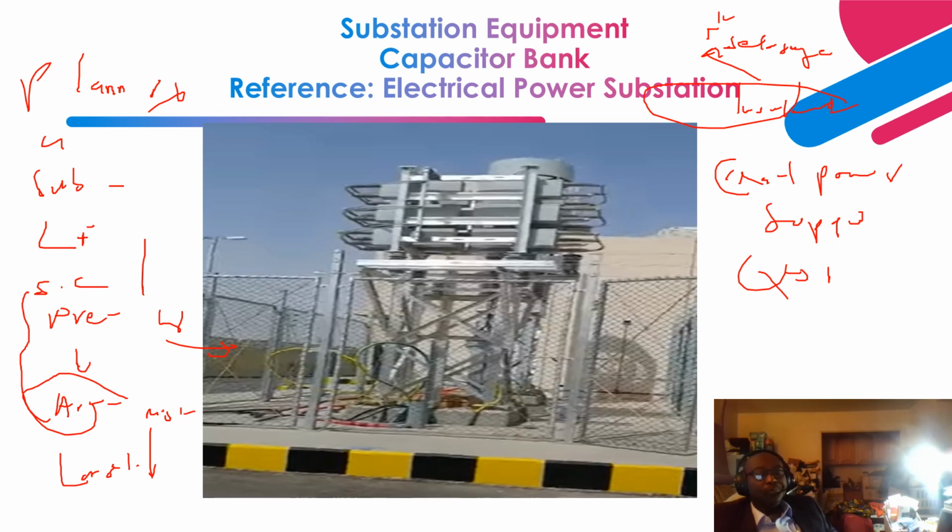If you do the load flow, that is when the discipline engineer and the architectural engineering consulting company do the simulation, and they find out that after performing the load flow, active power flow and reactive power flow, the voltage profiles on the buses violate the criteria.